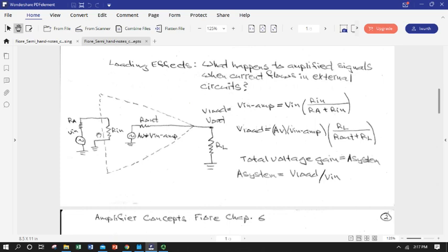We're not going to be sacrificing much of that input signal before it ever really gets into the amplifier to get amplified. Okay, so now let's look at the output. What we want is to get as much gain at our output as possible, but unfortunately we once again have a voltage divider working not in our favor. We've got our voltage source somewhere in the amplifier circuit that's going to act on whatever portion of our input signal gets into the amplifier.